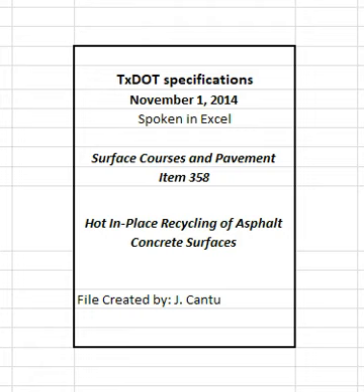On the first day of production, use the control strip method given in Text 207F, Part 4, to establish the rolling pattern that will produce the desired in-place air voids unless otherwise directed. Operate rollers in vibratory mode only when doing so does not damage the pavement. Establish a new rolling pattern when changes occur in the recycled mix or placement conditions. Adjust or cease compaction when cracking or displacement occurs. Ensure that pavement is fully compacted before allowing rollers to park on the pavement.